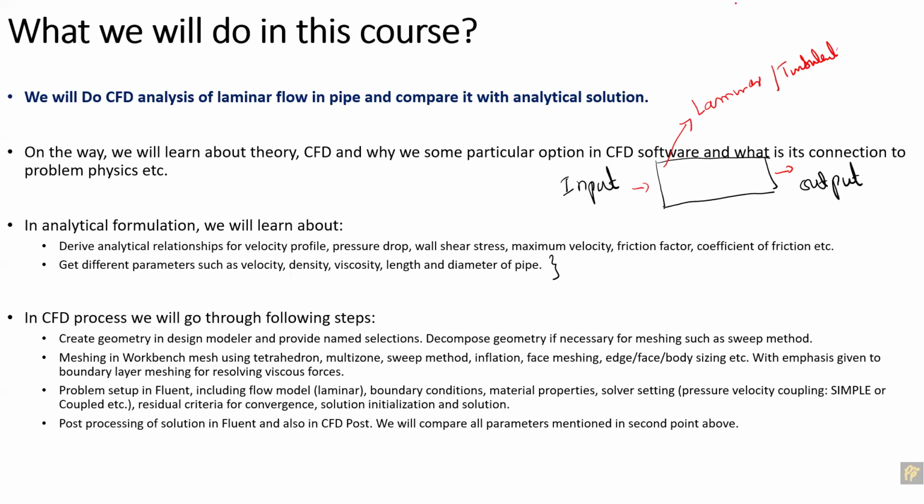For example, for high Mach number flows, the boundary layer is not important. The boundary layer is very, very thin. So in that case, the shock wave is important. Okay, so the shock wave is important, and in hypersonic flows, the heat transfer rates are very important on the body of, for example, a re-entry vehicle. So this should be known to you, what aspects are important for your case.